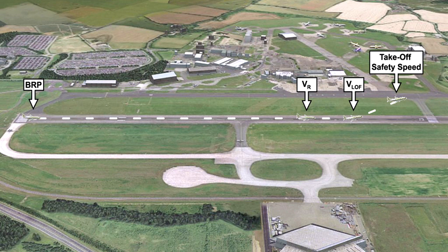There is a certain minimum value associated with this speed, which is usually based upon the aeroplane's stall speed and/or its control speed, but these will be dealt with later. In large twin-engine aircraft, the takeoff safety speed is commonly referred to as V2.